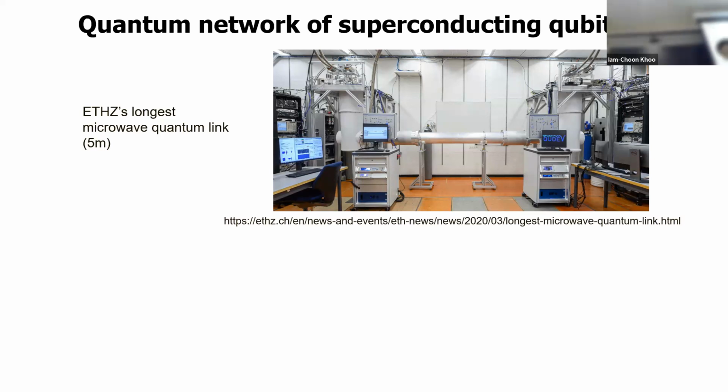This quantum interface is very hard to make. For example, one of the mainstream quantum computing platforms is superconducting qubits, which operate on microwave photons in a milli-Kelvin dilution refrigerator. Those microwave photons cannot come out to room temperature and maintain quantum coherence.